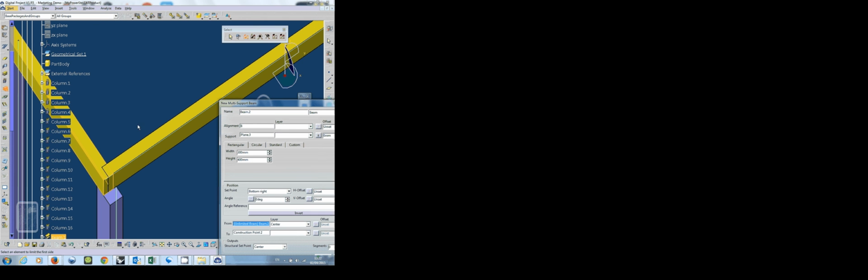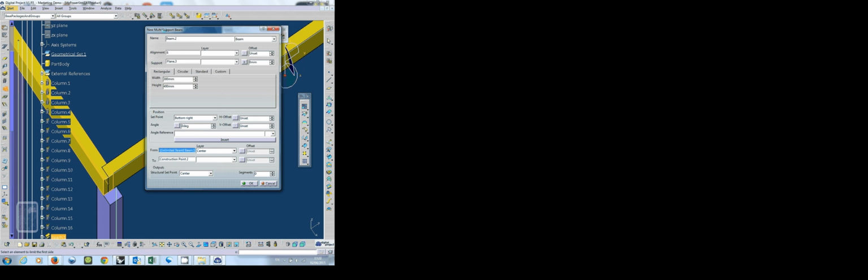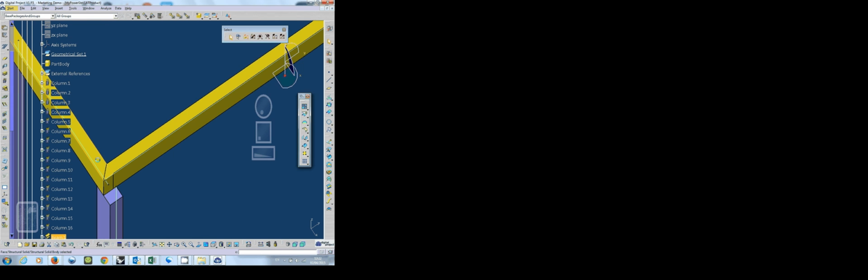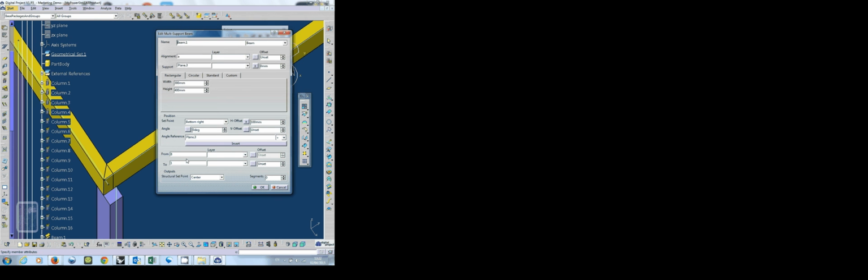In the real world it cannot clash. There are a number of ways you can do that. If you open that up, you can say, okay, I'm going to notch it, or maybe I will do a miter, which gives you a chamfered angle. This is minor, this is positive, like this, gives you a 45 degree, right? I will change the other one as well.